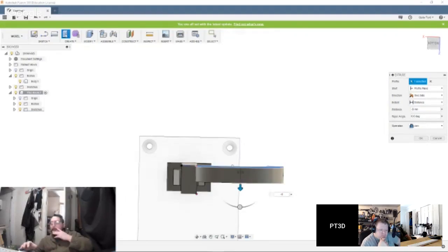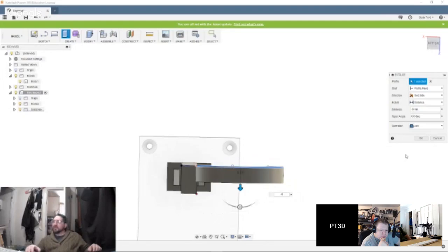Yeah, don't even hit a number unless you want a certain number. You want to just go down to that equal bottom face? Yep. Oh, that's right. Delete the number, because now that you've entered a number, it can't be there. And all you got to do is spin around and click on it. You don't even have to change anything. All you have to do is spin around and click on that face, and it will automatically know now. The latest update makes it so it automatically knows.